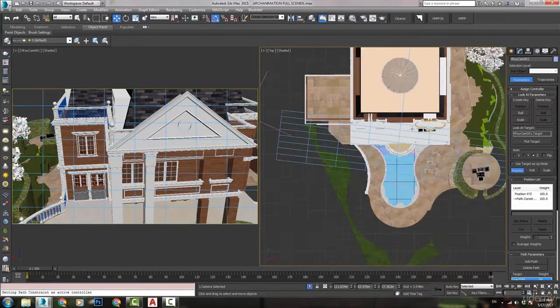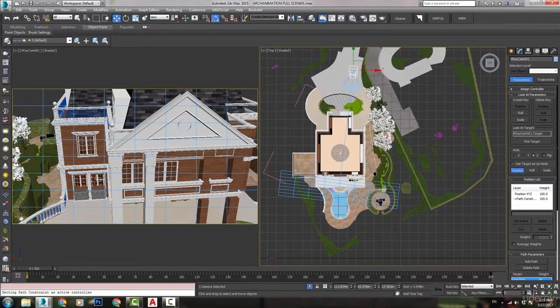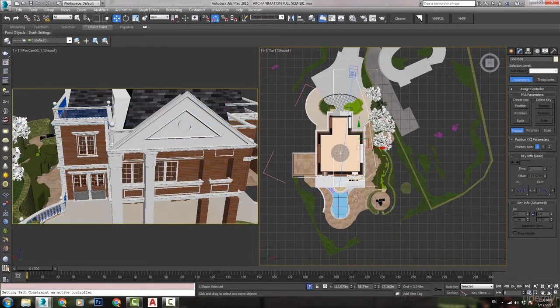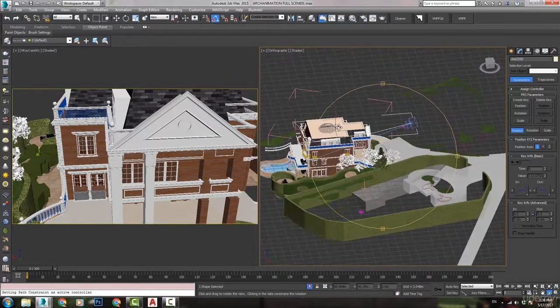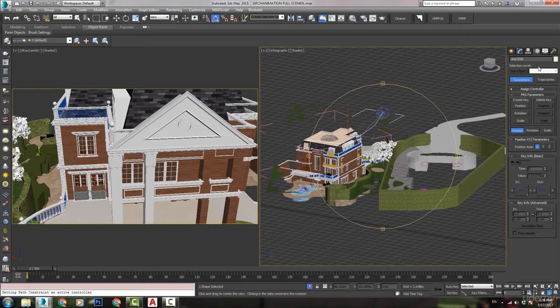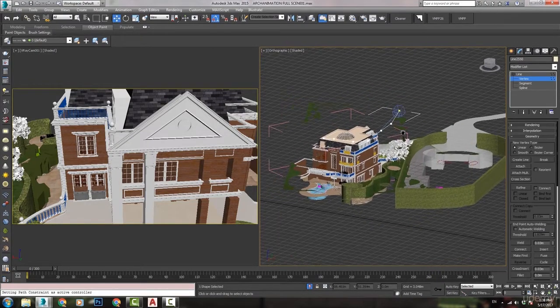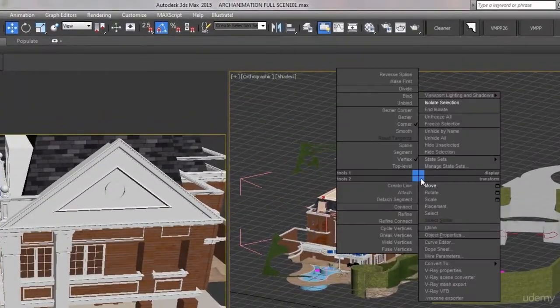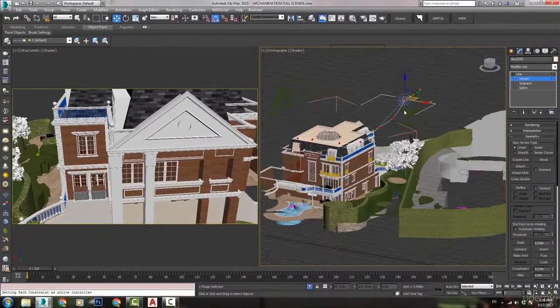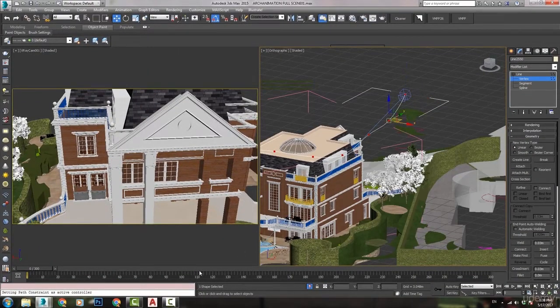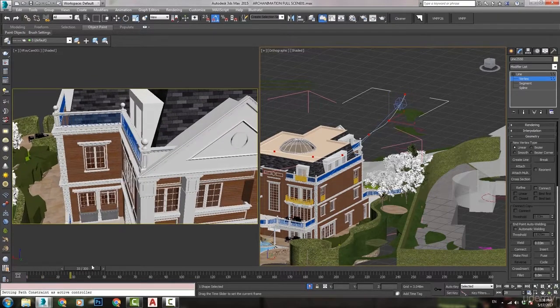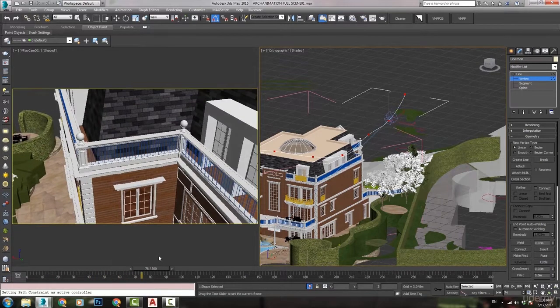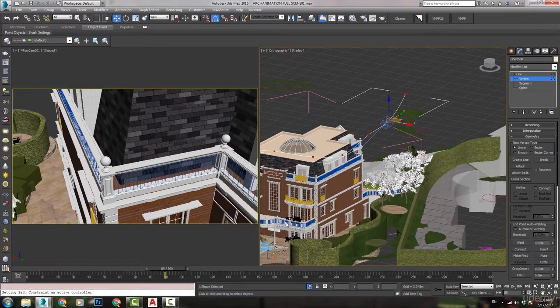Let's refine our movement by editing that line. First thing first, as a general rule, do not let the vertices be corner. Always make them smooth. Let's go to the line, go to the vertex level, select all vertices and convert to smooth. Why did we do that? Because if the vertices are not set to smooth, there will be an annoying sudden shock when the camera reaches a point that is set to corner, for example.